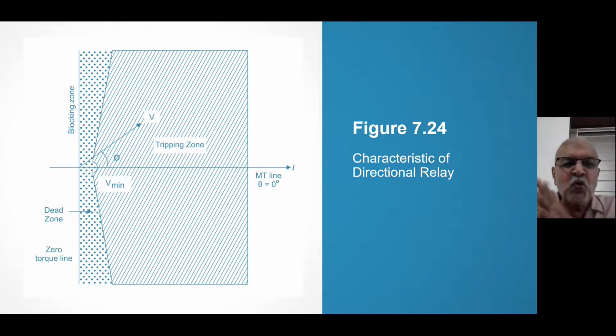Not only that, but I cannot keep the two contacts like that only. I have to have a slight bias of spring on the moving contact so that the relay does not operate by vibration. So I have to overcome that slight bias of spring. So a minimum voltage is required at 0 degrees, which is shown; the arrow is forgotten, but that is what we mean.